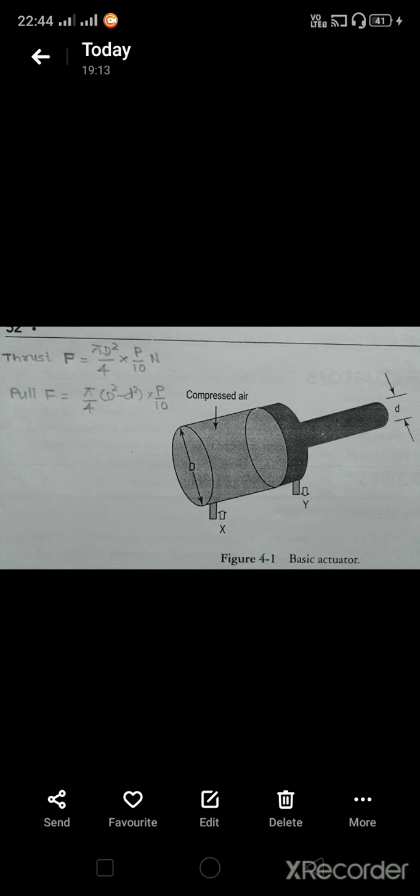see on your screen. An air cylinder is a simple, low cost, easy to install device that is ideal for generating powerful linear movement. Air cylinders are versatile and fast acting, and with the use of special seals they can withstand ambient temperatures even up to 250 degrees centigrade.